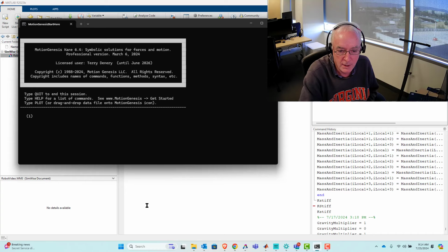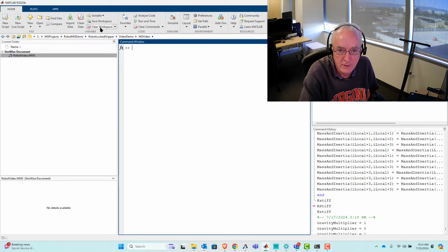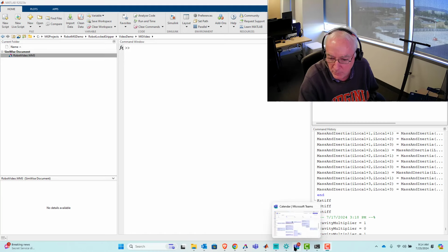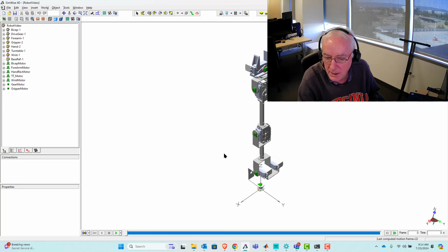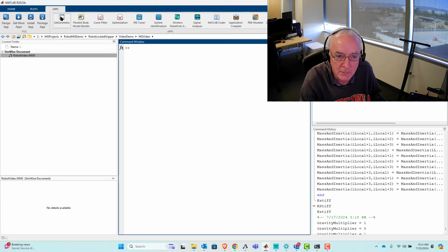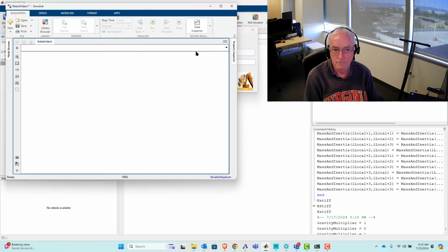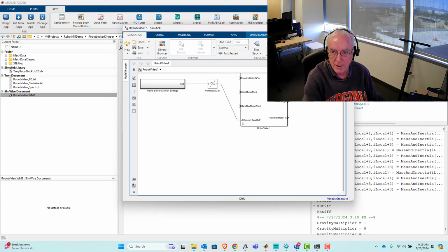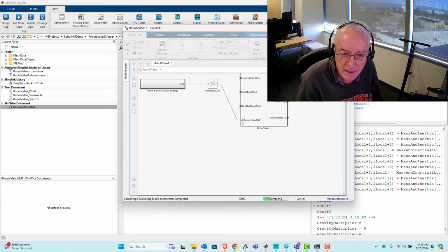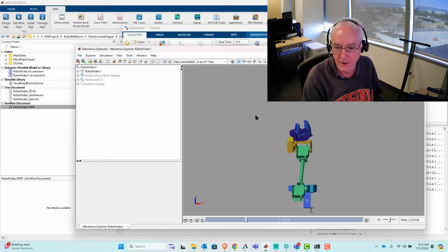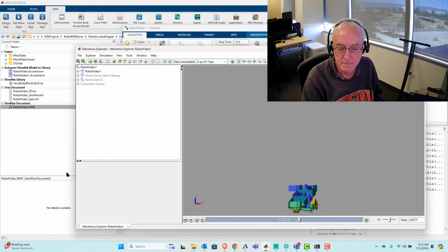All right. And so I think I'll start here. I created this new directory. I just want to do the fresh export one more time of the model that we created in the previous video. So I got it up and running right here. And let's go ahead and launch Get Geometry. Okay, so there's the Simscape Multibody model. I always like to hit the run button right off the bat. And we'll see our robot in a second, with the animation created with the STL files that were brought in from Simwise, right?